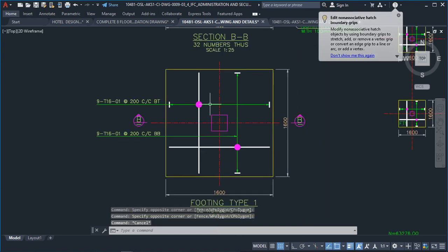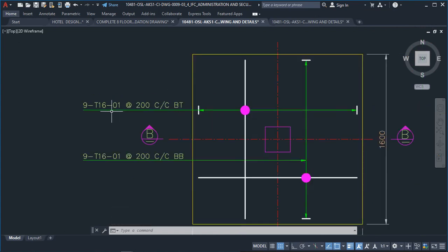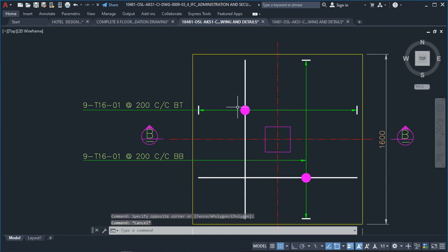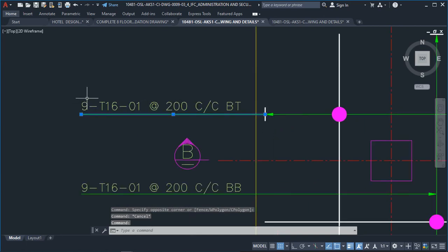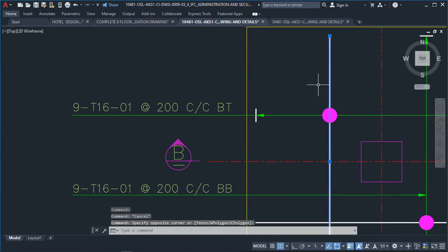Now, the next thing you will do is to call out the numbers of that reinforcement and the spacing. If this reinforcement is running from here to here, the next question someone reading your drawing will ask is, what is the spacing? How many of this reinforcement are going to run from this point to this point? That is when you have to throw out a line to call out the number of reinforcement and also the size of this reinforcement.